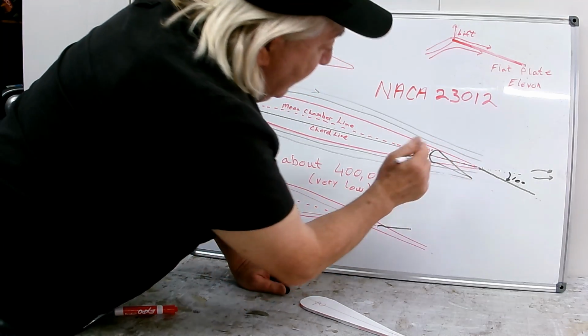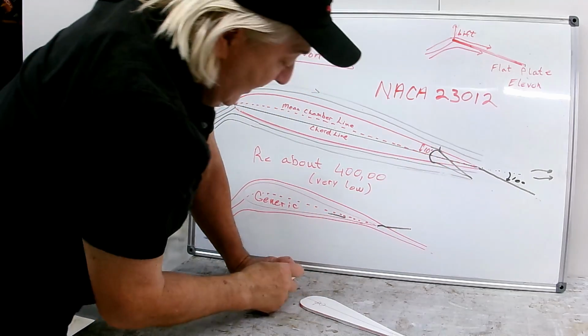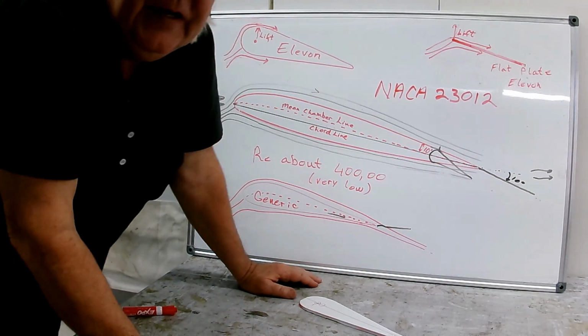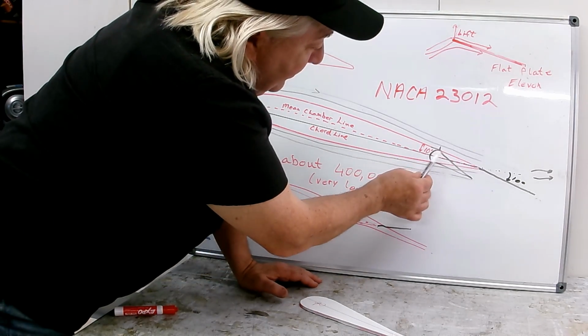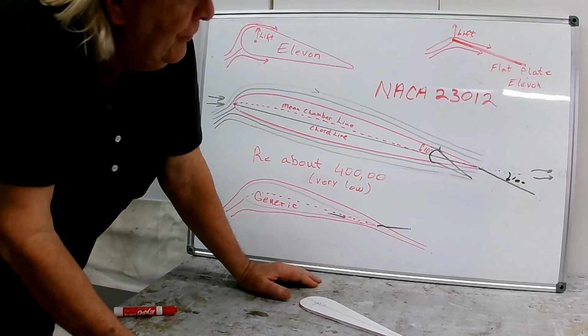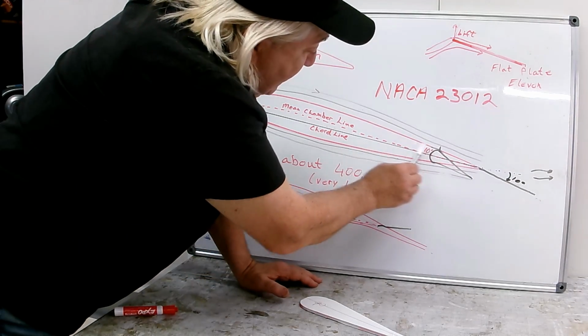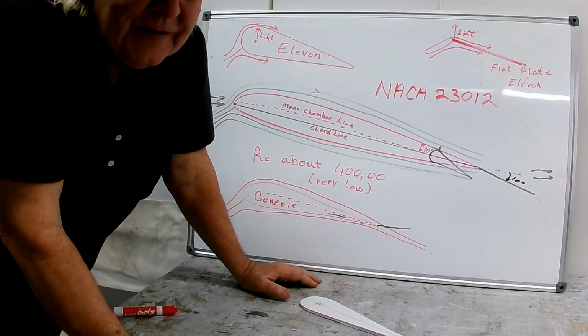Any motion that you make puts a discontinuity right here where you turn the corner. And by discontinuity, I mean discontinuity mathematically. And what this is, when you deflect the control surface and you have this discontinuity, that means that the first derivative that describes this shape, the airfoil shape and going around the corner, is discontinuous.